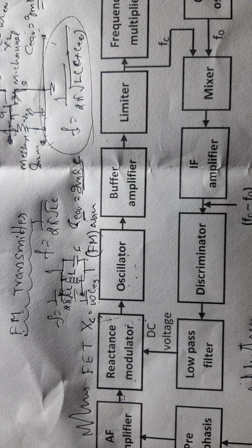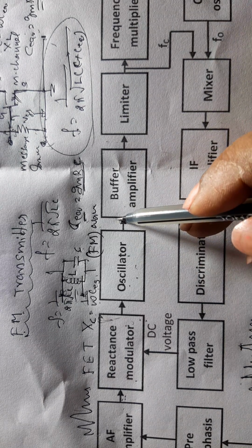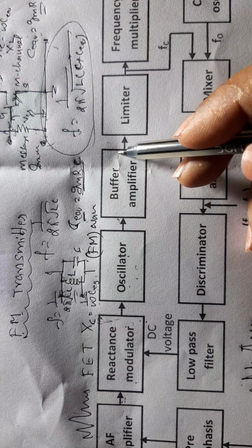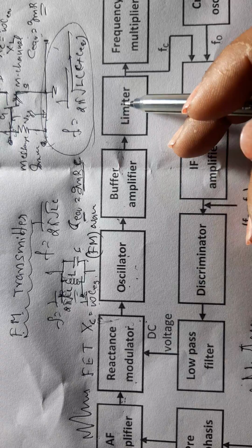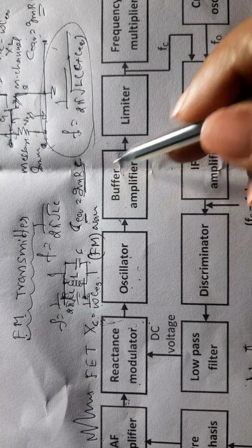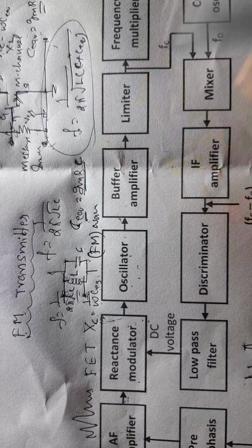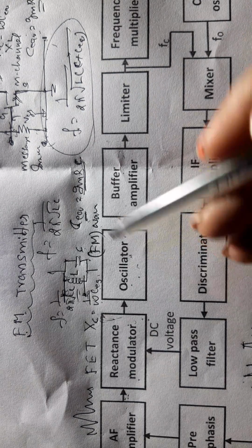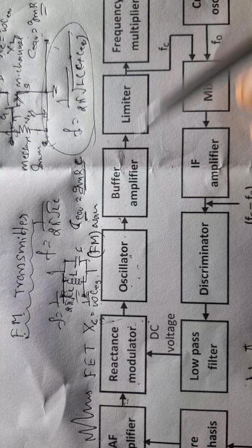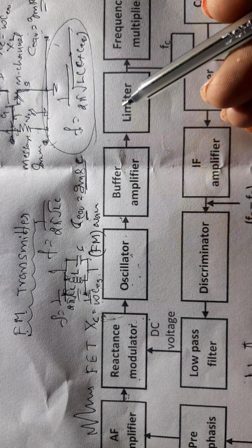When the output impedance becomes low, whatever signal comes from the oscillator entirely passes through that low resistance path and is fed to the next circuit. That means the buffer does not alter the output for the next stage. Therefore, it simply isolates the previous and the next stages. So the buffer amplifier is a common collector amplifier. It isolates the two stages, the previous one and the next one.